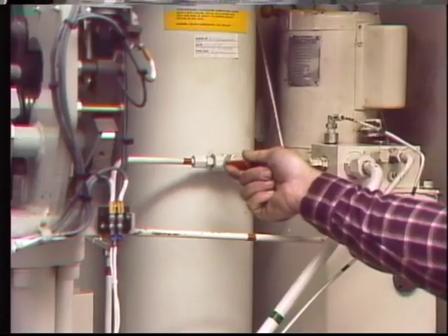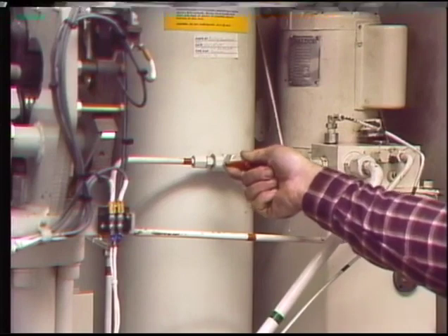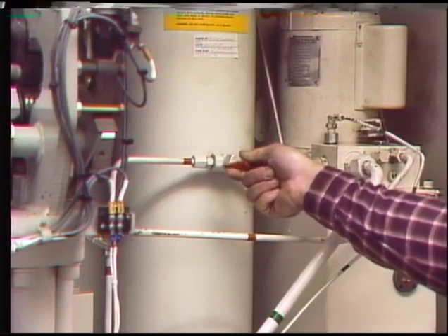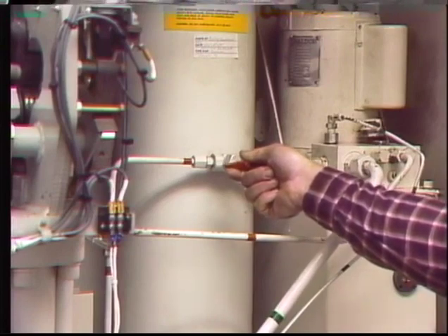On a hydraulic mechanism, a bleed valve is opened to bleed system pressure to zero so that the breaker cannot operate. Regardless of the mechanism involved, the breaker is isolated from the mechanism to prevent accidental injuries. Once that's done, work can proceed on the breaker.